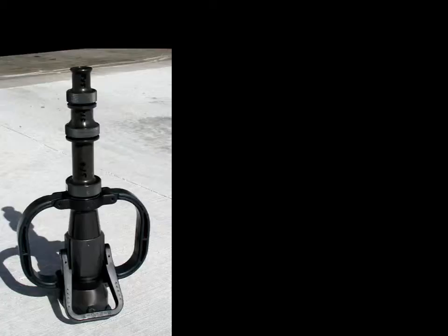And then we're going to get into some handline nozzle sizes and flows. At 50 psi nozzle pressure, a 3/4 inch tip gives you 120 gallons per minute. A 7/8 is 161, a 1 inch is 209, a 1 1/8 is 250 gallons a minute, and a 1 1/4 inch tip, you're going to get 330 gallons per minute, and that's normally out of a 2.5, the 2.5 being the supply for that line.